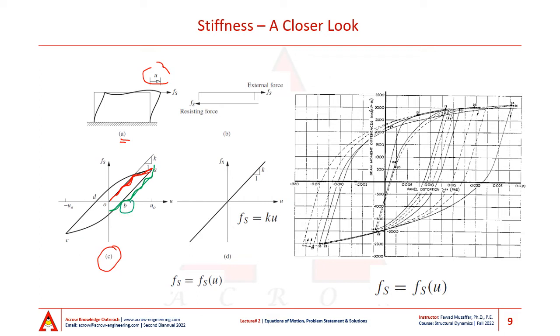and hitting the zero force response at point B. If the loading is now continued in the negative direction, this frame will continue to resist load, and the resulting force displacement plot will be shown by the branch BC on this plot. If at this stage the loading is now reversed, the reloading branch will be this curve through point D again to point A.